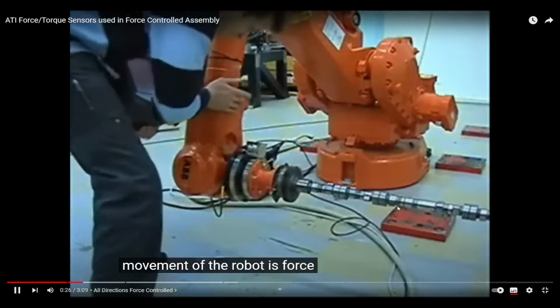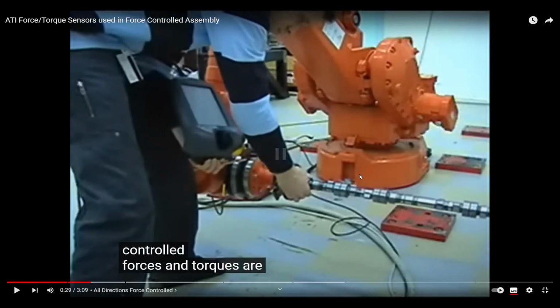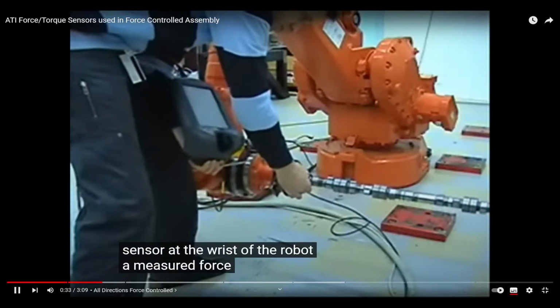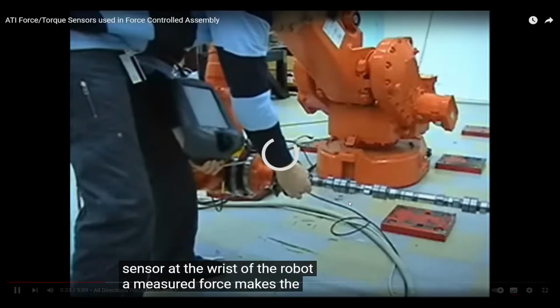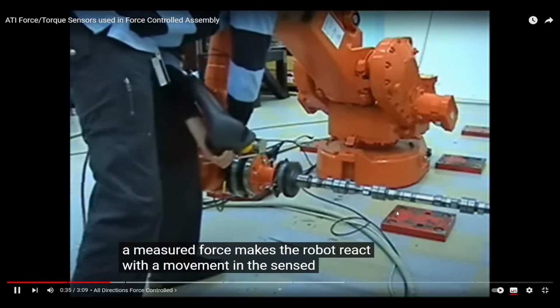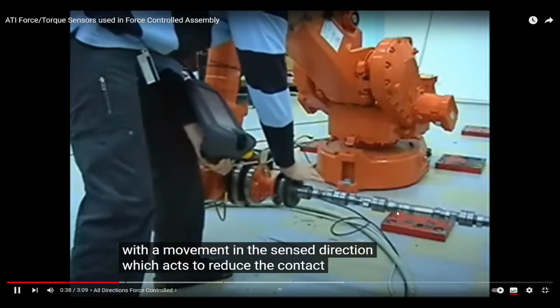Movement of the robot is force-controlled. Forces and torques are measured by the sensor at the wrist of the robot. A measured force makes the robot react with a movement in the sensed direction, which acts to reduce the contact force.